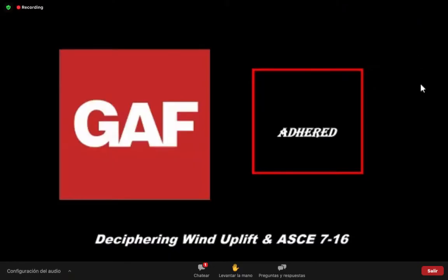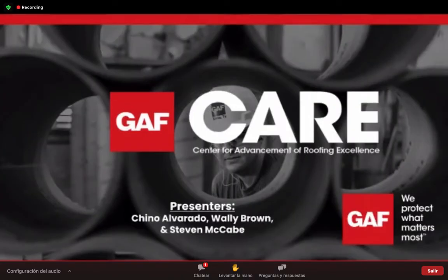And the last thing, Wally: here on the care team, once again, we try to give you as much knowledge as we can so you can take it to the field and help you with installing the roofs. But with ASCE 7-16, there are so many variables that determine how many fasteners per board, how many perimeter sheets, how big your sheets are, or your perimeter.